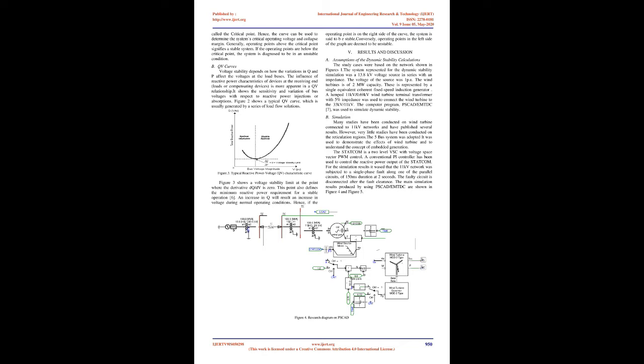Figure 3: typical reactive power voltage, QV, characteristic curve. Figure 3 shows a voltage stability limit at the point where the derivative dQ/dV is 0. This point also defines the minimum reactive power requirement for a stable operation [6].